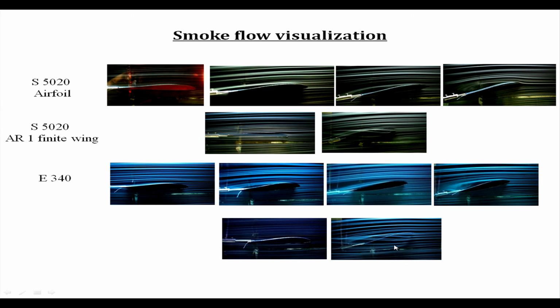In this part, to get the color, well, this is not blue smoke, by the way. It is just the lighting which gives you that. The background is black, like in oil flow, what we are doing, yes, same thing. Matte finish, it shouldn't be a shining surface, right? And of course, illumination is from the top. Try to get your optical access as good as you can, right?